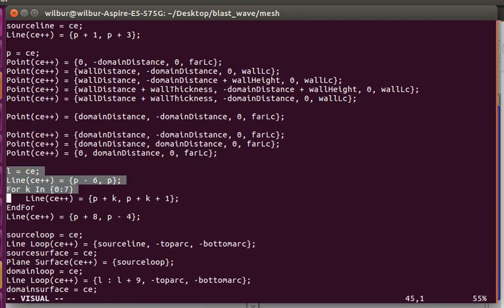And these lines just basically iterate through the points I've just created. You'll notice that I put these little markers here to denote the beginning, and since I do that, I can reference it by offset, and just with this for loop generate all the lines in sequence of the points.